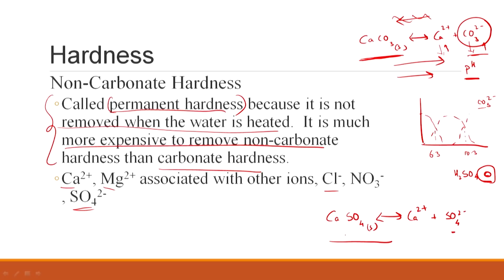Why is that? Again, if you wanted to go in this way, you need to disturb the equilibrium. For that, you need to bring down the concentration of these reactants that are in equilibrium with the scalant, or the precipitant. And as you see here, to bring that down, the pH has to be really low because the pK is pretty low. That is something that we saw here. That is the reason why we typically refer to such precipitates as permanent hardness.